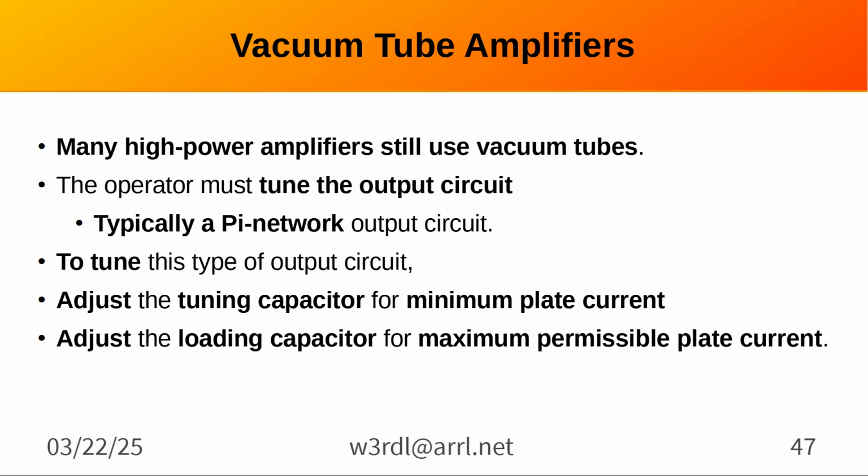Plus, in this case, you're going to have probably a pi circuit that, when it's tuned right, is going to be around 50 ohms. Well, the transistor has a low impedance. Right. Yeah, well, tubes have high. But if you notice, most transistor amplifiers, because you're operating them at relatively low voltages, are going to go through a step-up transformer.